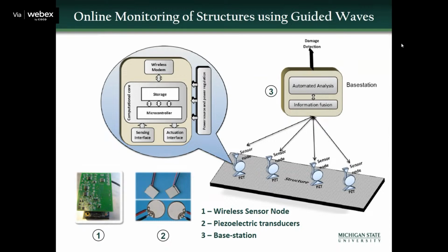So this is a schematic of a funded project from, I believe, about 10 or 11 years ago at MSU, where we developed an online structural monitoring framework using guided waves. Multiple sensor nodes are shown here on the structure, where each sensor node is implemented using a PZT sensor.